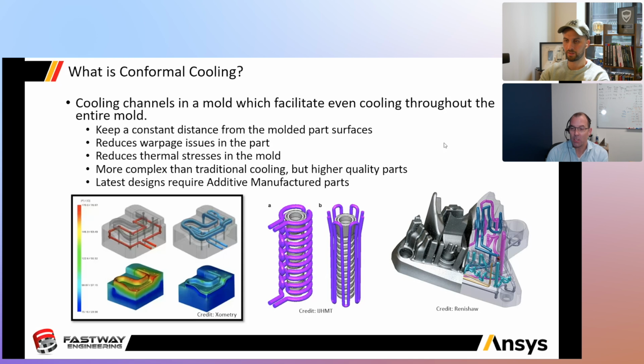We're melting and injecting a liquid polymer, and then we're cooling that polymer so it solidifies. And we're doing that quickly. In plastic injection molding, we're looking at cycle times at most, maybe in large parts, maybe a minute, and for some small parts, and today we're going to be talking about a pretty small part, we're talking about seconds. So this is what we would consider to be medium to potentially high volume production.